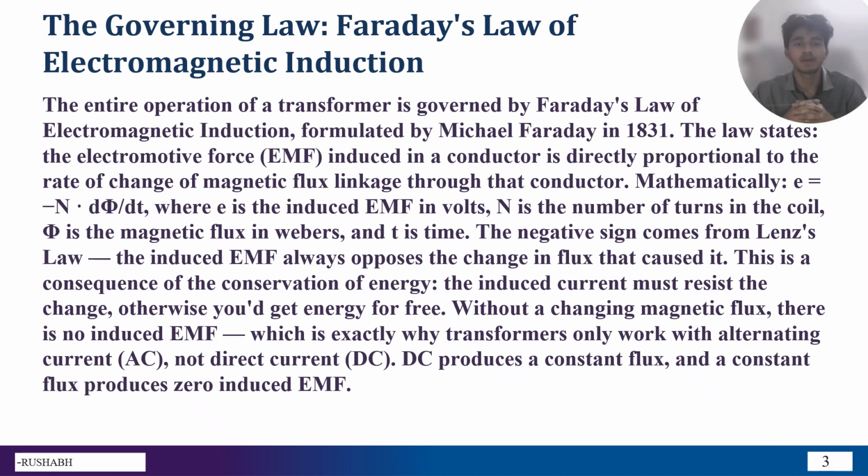In this slide, we are going to learn one of the main laws, the governing law of transformers, known as Faraday's law of electromagnetic induction. The entire operation of transformers is governed by Faraday's law of electromagnetic induction, formulated by Michael Faraday in 1831. The law states that the electromotive force, EMF, induced in a conductor is directly proportional to the rate of change of magnetic flux linkage through that conductor.